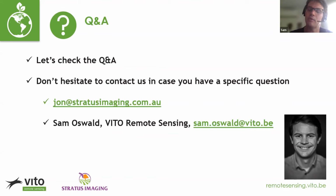Here, rather than producing orthomosaics, we will capture a single image using RTK drones, with very precise GPS coordinates, to try and capture an entire plot in one image. And then you will not have so many issues with the alignment.